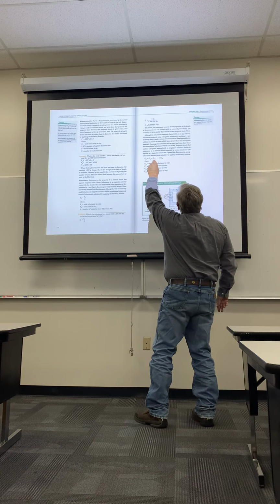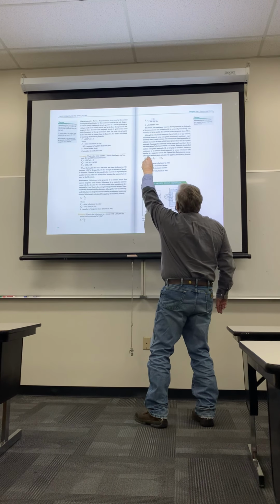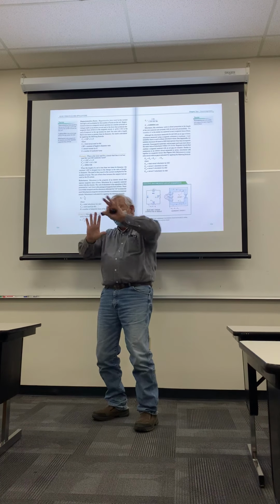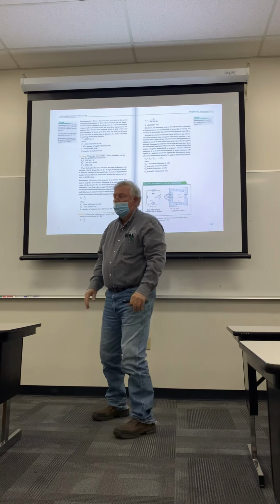It's mentioned a couple times in there. But if we take the 2 Gilberts and divide it by the 4.5 million Maxwells, we get this reluctance of that many rels. Sort of like the resistance to magnetic lines of flux. Okay?